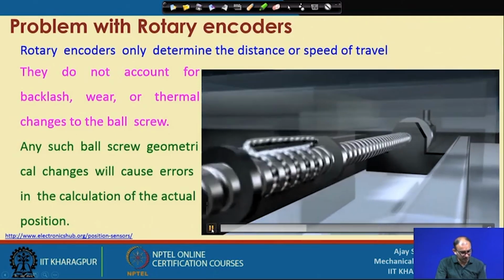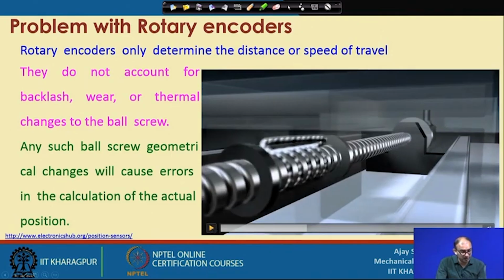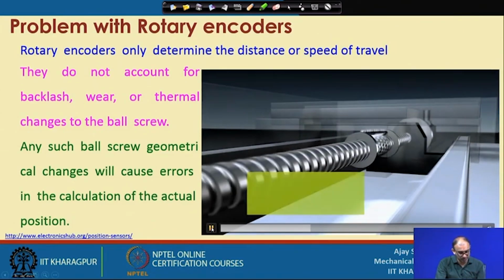What is happening is that when it is moving, even though it is a recirculating ball screw kind of thing, with the linear guide that we have seen long time before, the balls are recirculated around this particular system, and you have a point contact or line contact of many balls. It will reduce the friction between these two. But still, if you are moving this hundreds or thousand times, then obviously there is heat generation, and that heat generation is enough to get some backlash here. So, what is the axis drift?